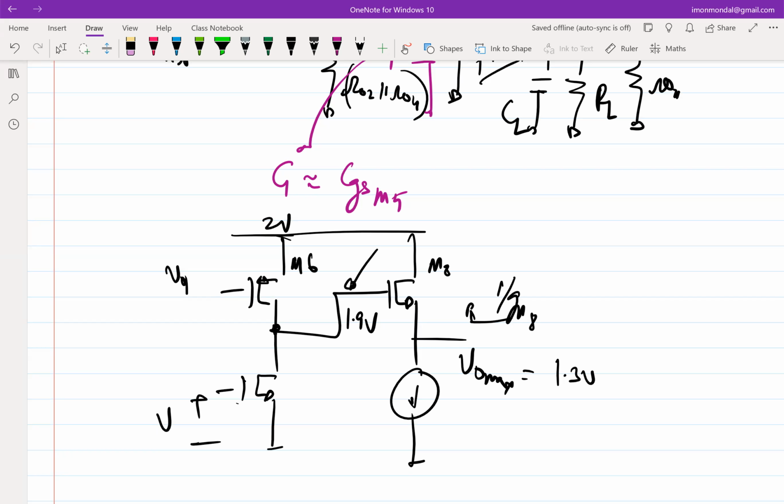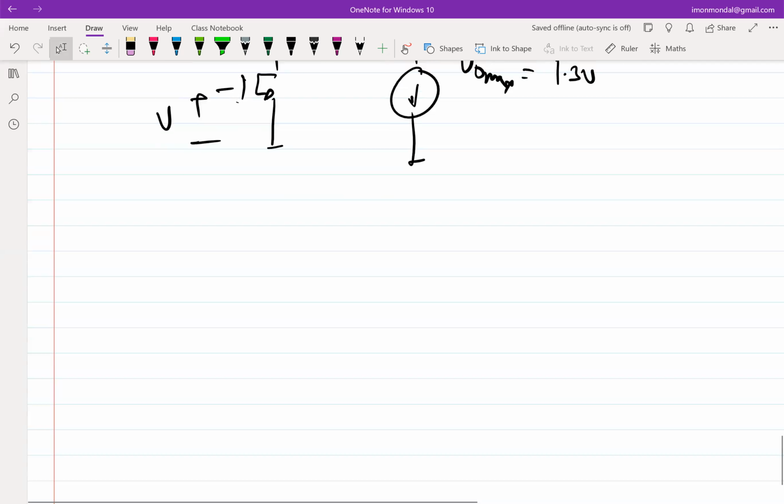So we say that we get rid of this third stage, which is the buffer stage, and still use it as an op-amp. Why? Because ultimately we'll be putting everything in negative feedback. And when we put everything in negative feedback, the output impedance anyway goes down. So ultimately, this is what is happening. If I draw it in this format, you'll be able to understand better.